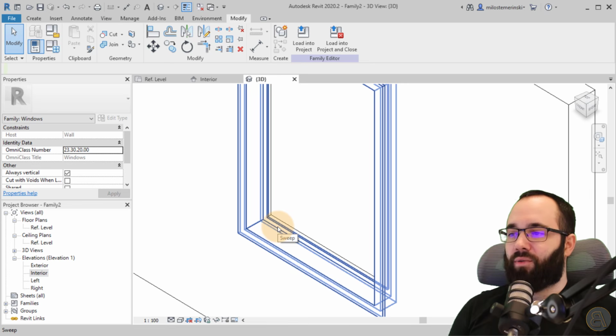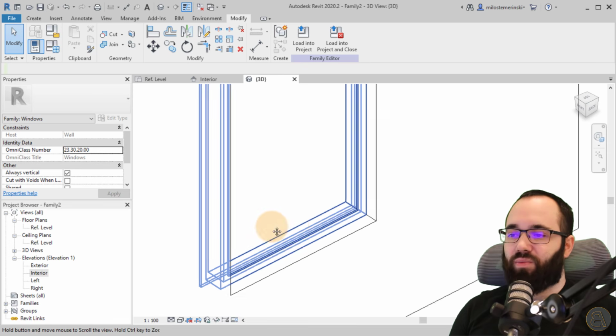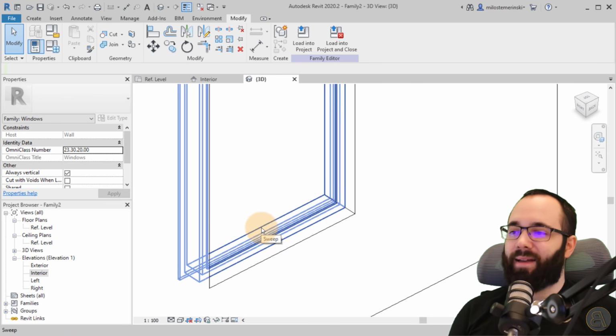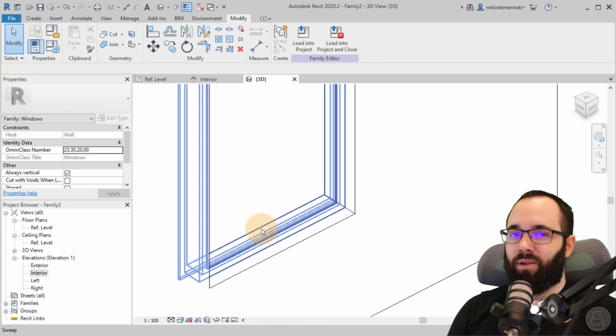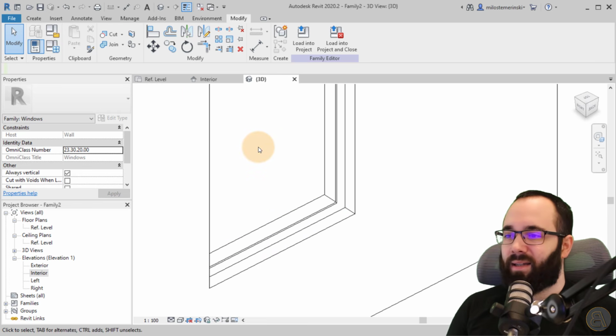and as I said, this is beginner to pro. So the pro side of this is we're going to have a double frame. So it's going to be one sweep on the inside and one sweep on the outside, and the end result of that is going to give us a frame where we can apply different materials for the inside of the house and then different materials for the outside of the house, or outside of the window, exterior side. So for example, if you want to have a white window on the facade, you can have white on the facade, and then on the inside for the interior you can have like a wood material or something like that. That can just make it a little bit nicer, add a bit more complexity. Okay, so let's move on.